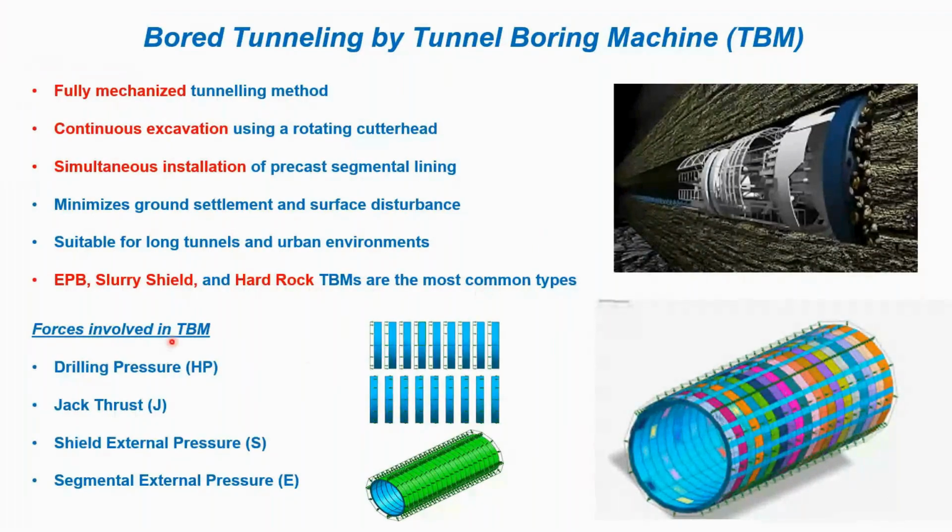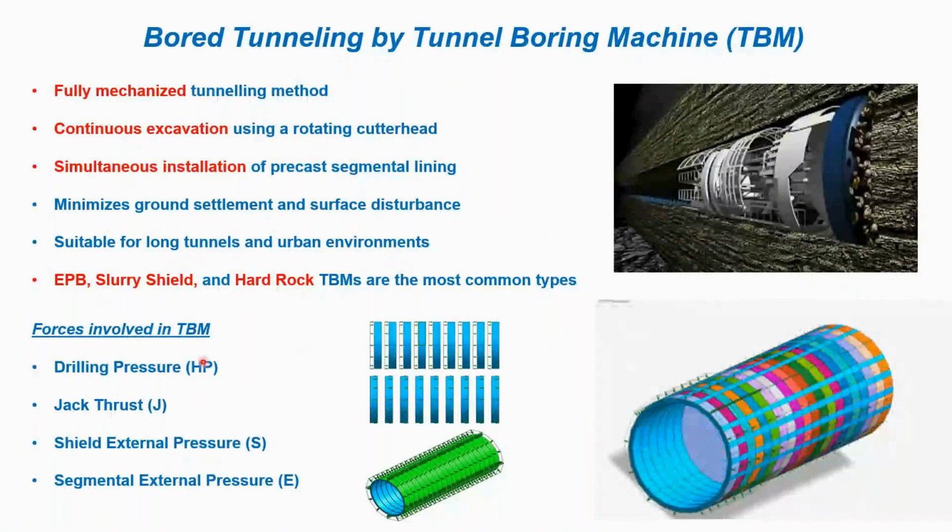However, if we want to simulate this sequence in the software, we need to consider all the kinds of forces or pressures involved in the TBM operation, like the drilling pressure or face pressure, which is applied at the excavation phase, and it prevents collapse of the tunnel face and balances the earth and groundwater pressure. So this is critical for controlling settlement and face stability.